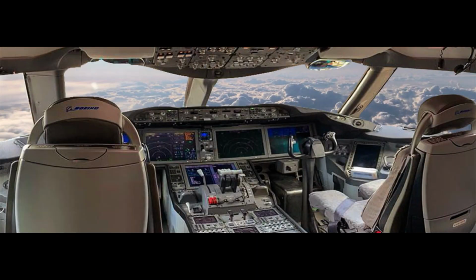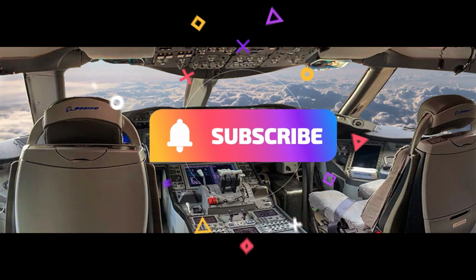Disadvantages of using the FD/autopilot include the following. 1. Forgetting to maintain manual flying skills. It is important to practice flying without the FD/autopilot often enough to maintain proficiency in basic flying skills and the instrument crosscheck and scan. One common pitfall of advanced avionics is the pilot's tendency to forget to maintain hard-earned skills for instrument flight. All equipment will fail at some time. The competent pilot is ready and prepared to make a transition to aircraft piloting at any time.